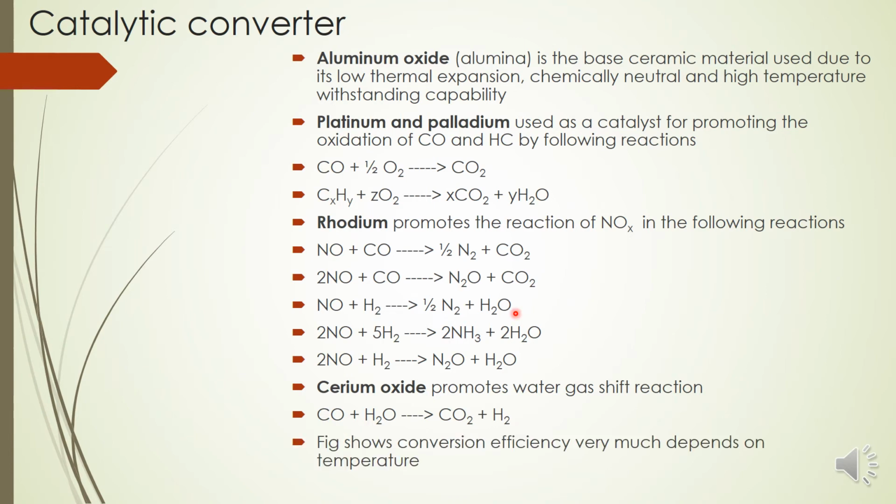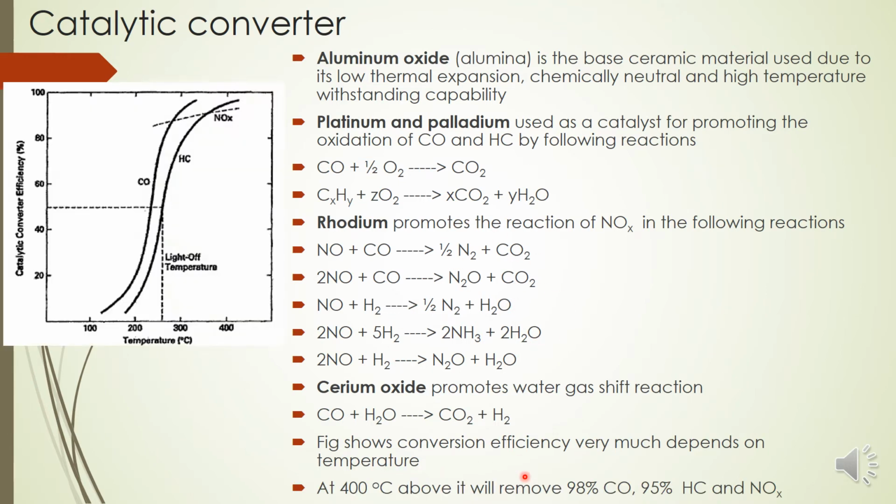And what is conversion efficiency? Conversion efficiency is how much of this gas, what percentage of this gas, will be converted to these products. That depends on temperature. We can see here the conversion efficiency versus temperature graph for a catalytic converter.